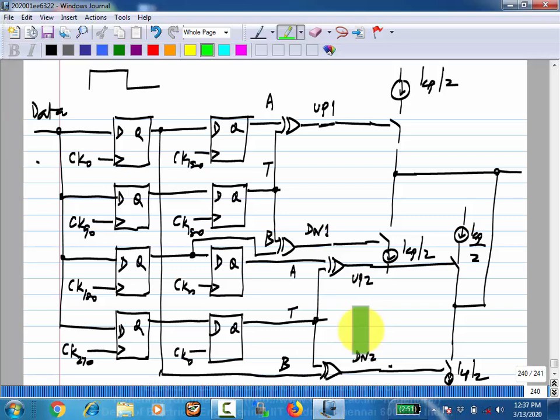If you want all of them to change at the same time so that you can use a single charge pump, you have to delay one of them by half a clock cycle. So that means that on average, for some of the transitions, you have a delayed measurement. On average, the latency has increased. Okay. Is this fine?